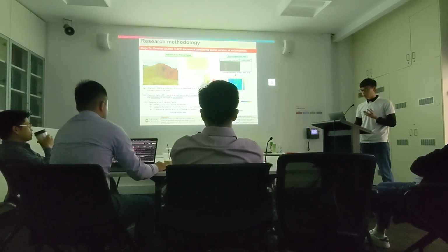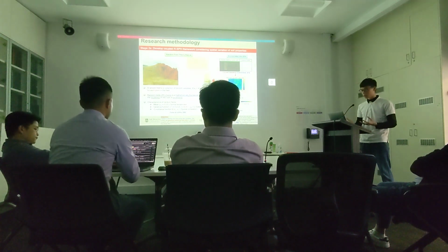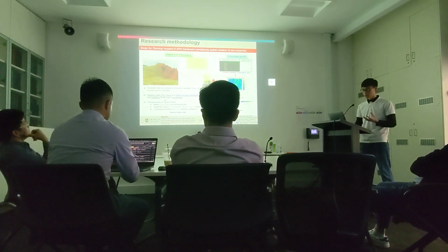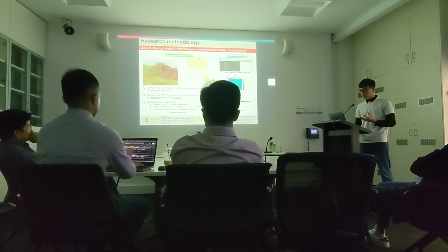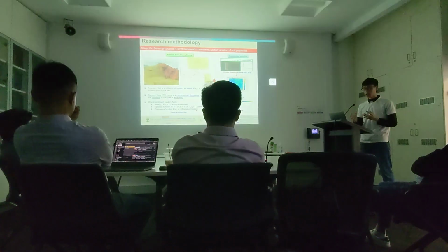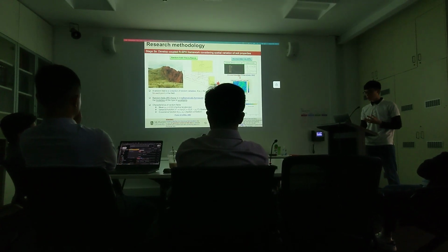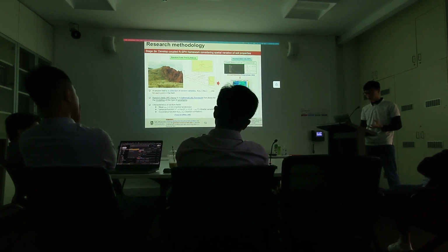Here, it gives you information like the central tendency or the spatial variability, which can be represented by the mean, variance function, or standard deviation. The next picture shows you the spatial correlation. We call it the covariance function. After all of that, we choose the method, and we can generate a numerical field like this, and we assign it to the particles in our numerical tool.